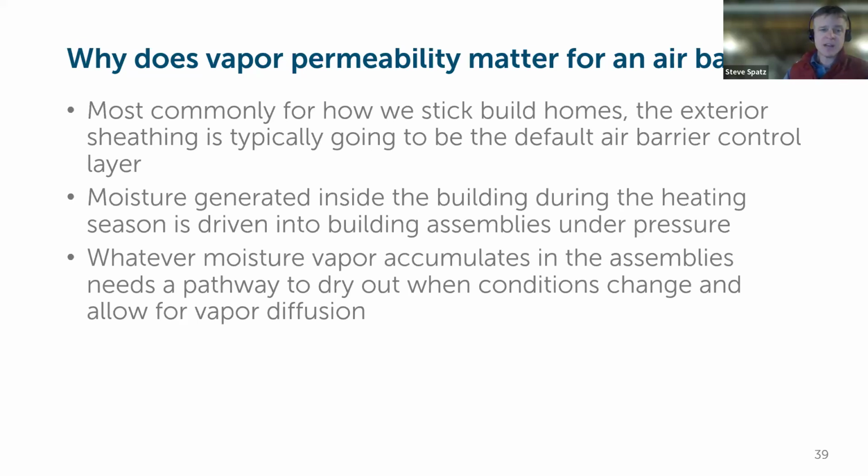But we have to accept the fact that there's going to be a certain percentage and volume of moisture vapor that makes it into building assemblies during a heating season. That's when things accumulate because of that pressure differential, because of the dynamics of drying capacity, because of temperature as well. So this is the time of year where we see moisture loading really happening within building assemblies. Because the mechanisms for drying do not exist easily and freely at this time of year. So you're going to see loading of moisture within walls and roofs and assemblies this time of year.